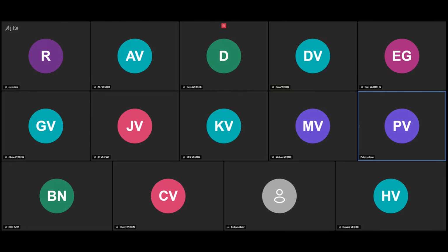Okay, all right. And one other thing I'll comment on, and then I'll turn it back: I had a bit of trouble setting the voltage levels to trigger on. I could set one not too badly, and then the other one was a bit of a problem. I adjusted the positioning of the traces, and that got me a little more level out of the voltage level to where I needed it. But sometimes I just couldn't quite get up there. So I'm not too sure what was going on with that. Have you ever had any trouble setting your voltage levels at all, Dave?